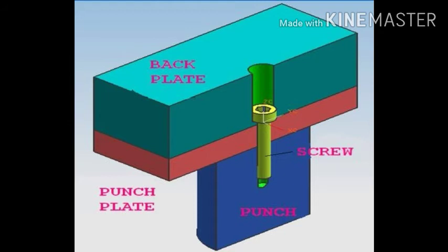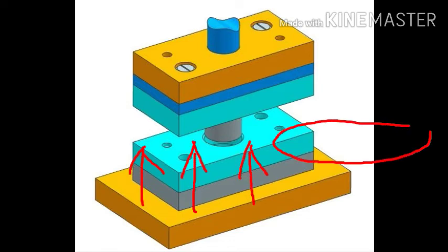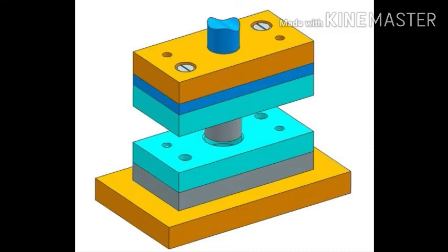Now we are focusing on the shank. The tool is located and clamped to the press ram by the shank. A C-shape or H-frame press machine has a ram which is attached to the tool by using the shank. The diameter of the shank for a particular tool depends only on the diameter of the corresponding hole size in the press ram.